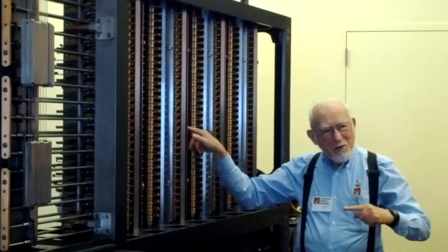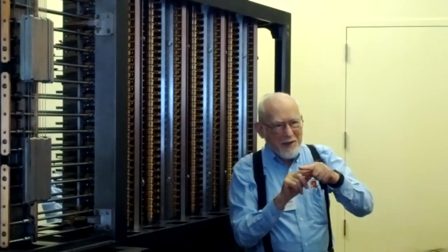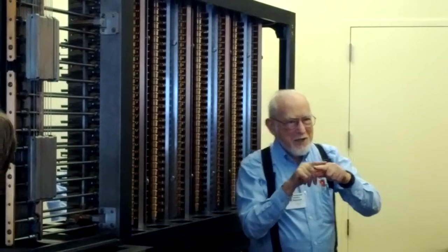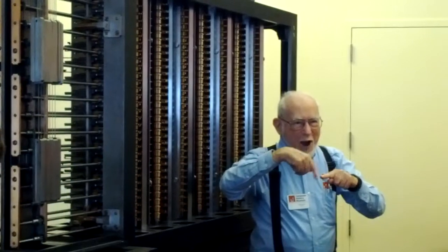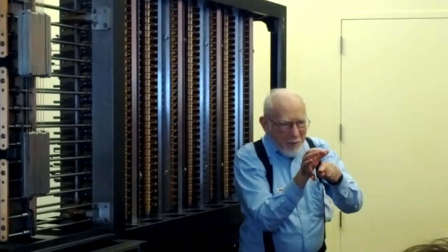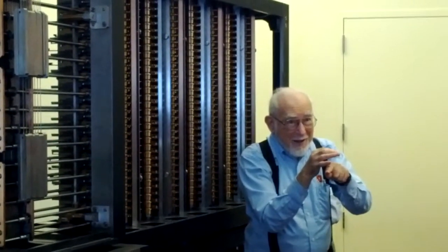And when that wheel goes through 0, or hits 0, it hits a part of that carry lever, and it moves it 1 little notch to a position saying, I need a carry. And in that new position, the spiraling thing can whack it. And when it whacks it, it moves it further. And then a part at the upper level adds 1 to the wheel above. So now if you had added 1 to a bunch of 9s, the carry could triple up the machine. And that's the best I can do with the carry.